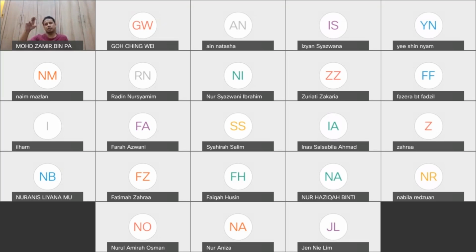So the mask resolves the features much better so that printing can be formed better. If you see on the slide, the features without PSM, or a phase shifting mask, the line in the center is not printed, but with PSM you can see that the line is printed, because the first one cannot be resolved well and the second one can be resolved better by PSM.